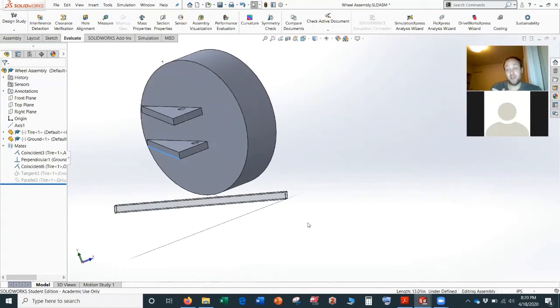I think this is a lot of what's happening in the Baja car. What you'll see is that when we do a lot of this on the Baja car, we give quite a bit of caster, quite a bit of scrub radius, and when you turn to the right, you'll have additional weight on the front right wheel, and you also see additional weight on the back left. So if you picture it kind of a square, let me allow some annotation.